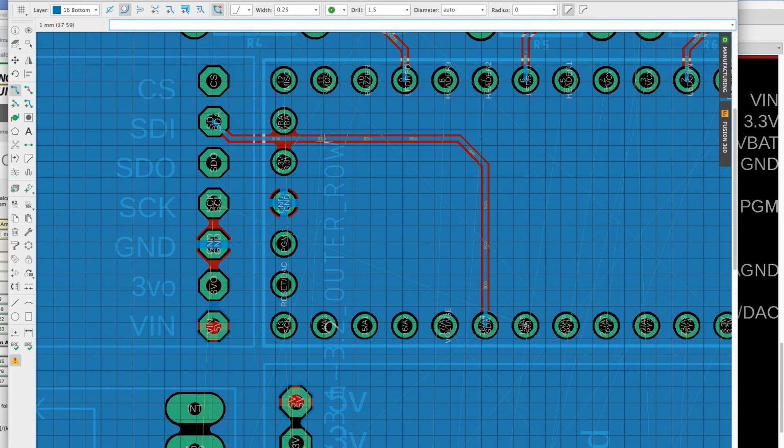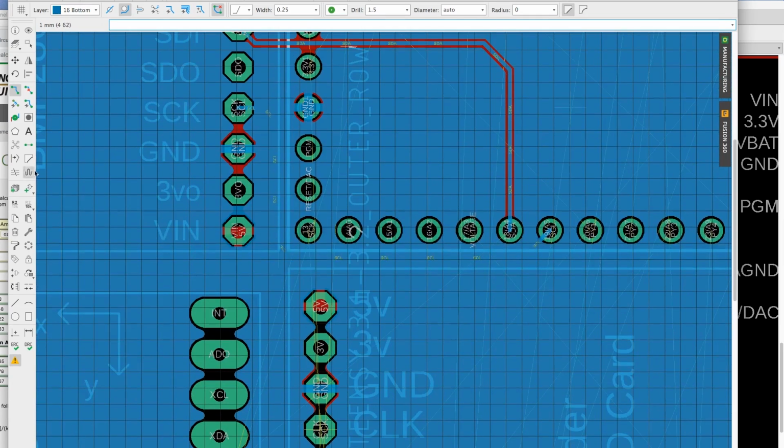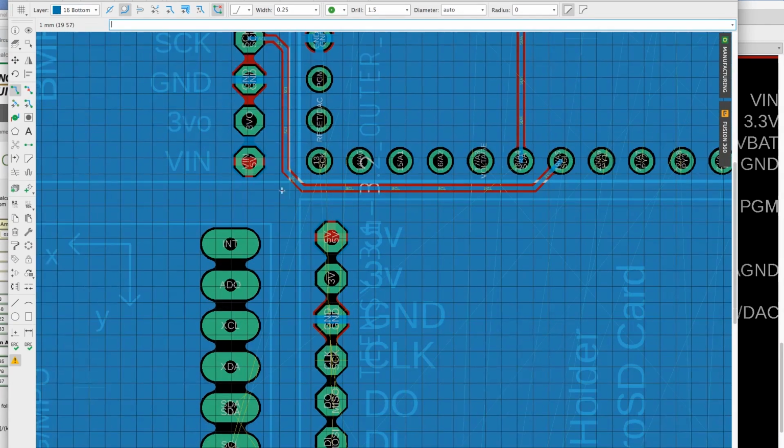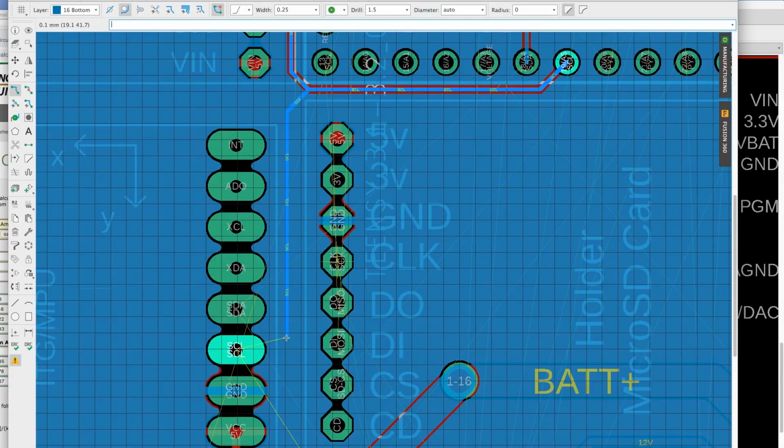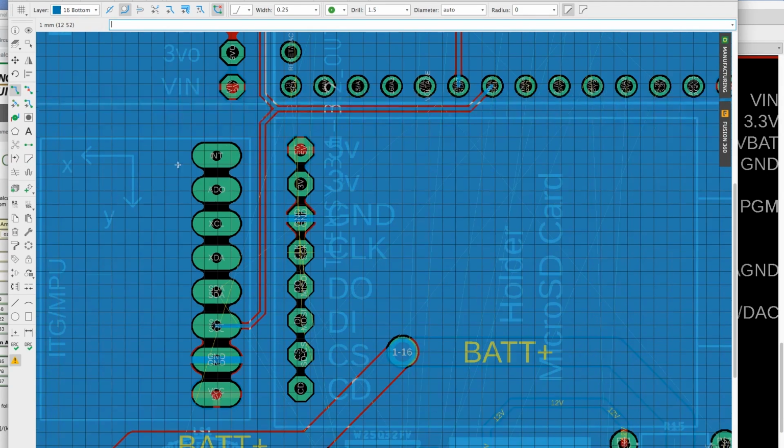And then the SCL line, we can actually cut through here. So I'm going to go below. I think the way I'm going to do this is I'm going to have the SCL line go between these two items, and then it's going to split off. First it's going to come up and go to the barometer, just like this. But we also have an SCL line that needs to go to the IMU. So I'll click out of here. We'll have it go down this way, SCL, and it goes 45 degrees. There we go, and we'll connect it to the IMU there as well.